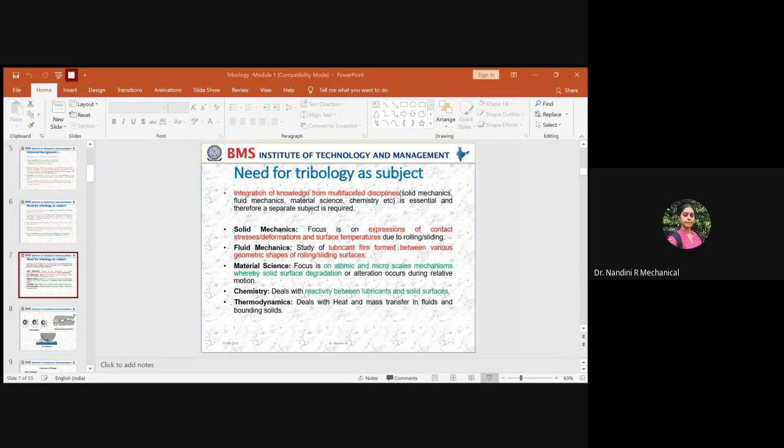Adhesive wear occurs across an uneven surface. You can see here the uniformly plated carbon graphite seal. When the uneven surface comes into the picture, it leads to a reduction in mechanical contact area. You have some uniformity here, and again some slant areas here in the carbon graphite seal. This type of variation will result in an increase in the level of stress, and hence there will be a chance of failure because it will be rotating.